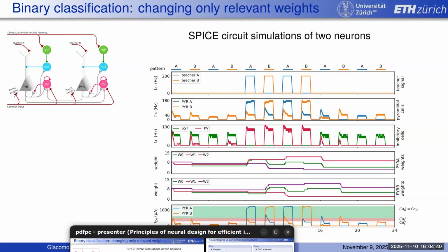And this data here is data from silicon simulations. It's done on Cadence with transistor equations and everything run through Cadence. So it takes actually a whole night to simulate 2 neurons and 3 synapses per neuron. So this was very, very CPU intensive. But it's actually faithful to what's going to be on the chip because it's really circuit simulation with noise and device mismatch and everything.